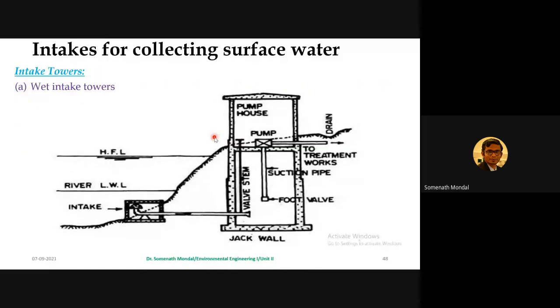So the withdrawal pipe may lie over the bed of the river, or may be in the form of tunnels below the river bed. Openings are made into the outer concrete cells as well as into the inside shaft. Fine. Gates are usually placed on the shaft so as to control the flow of water into the shaft and into the withdrawal conduit. Now, the water coming out of the withdrawal pipe may be taken to the pump house for lift, or may be directly taken to the treatment plant at a lower elevation.